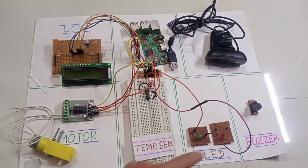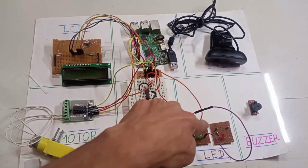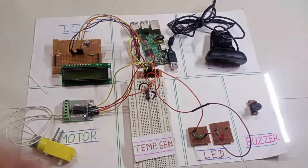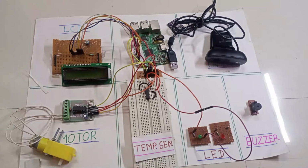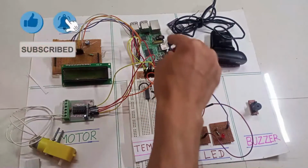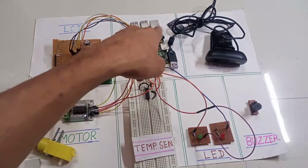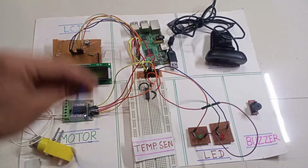Okay, now the same for the red LED, which again has 2 points, one VCC and one ground. One point should be connected to a resistor, and from that resistor we are giving the voltage supply or connecting to the Raspberry Pi. The other point again goes to the voltage supply or Raspberry Pi. Now the second point of this LED works as a ground pin, so I will take this pin and connect it to common ground again. Then this point of the LED should be connected to Raspberry Pi pin 33, so I will connect this pin to Raspberry Pi pin 33.